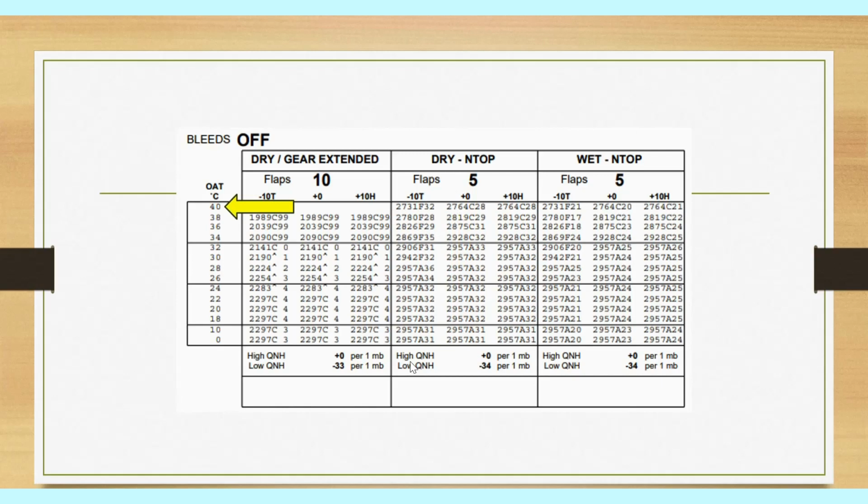Okay, so that's going to be our assumed temperature again. All right, that's assumed temperature. It means that we can assume a 40-degree environment outside. In actual fact, it's just 36, it's 4 degrees less. Okay, but the whole point, once again, to repeat, is to save engine life. We are fooling the engines, all right, literally, to tell them that, hey, the outside air temperature is quite hot, but in actual fact it isn't. Okay, good, very nice.